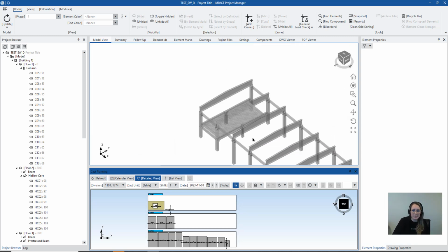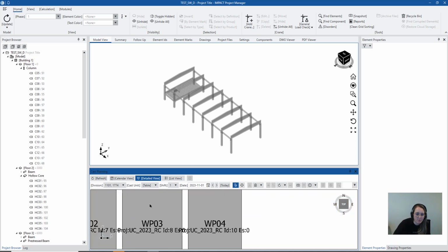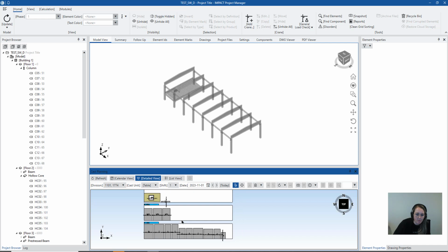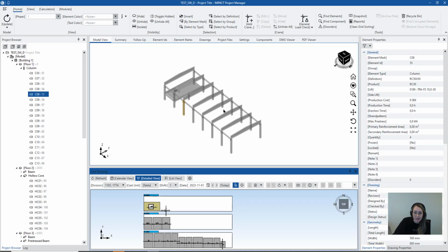But just to demonstrate that once you have your precast detailing here in Revit, you go and move further with the project. These are some walls drawn in Impact for Revit. You go and use it further where you're going to plan your precast beds. These are some beds for producing the elements, planning the transport, and so on. You can also take reports out of it. Everything is now in the database about these details. You can use the full potential of Impact.